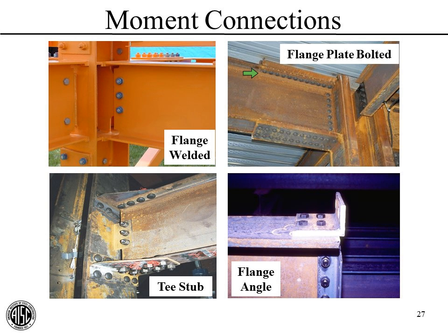Okay, here's a flange plate bolted connection. These plates are probably welded on in the shop, and then the connection is bolted up in the field along there. There's a T-stub moment connection, and then a flange angle moment connection.